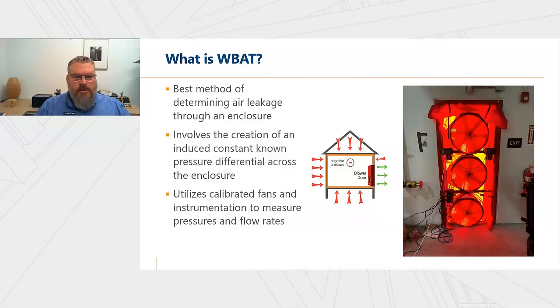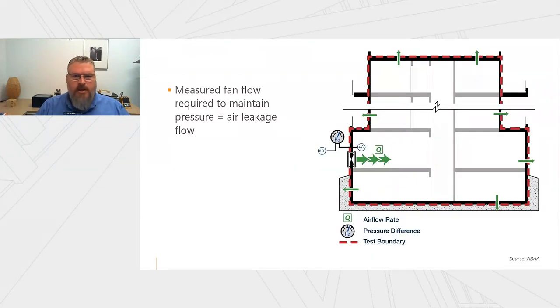And then, of course, we're using micromanometers to measure the pressure differences, typically between the interior and exterior of the building. Sometimes if you have a lab enclosure or an auditorium separation or something within the building, that might be between two spaces. But usually when we're talking about this, we're talking about the inside to outside delta P, or the difference in pressure. And theoretically, it's pretty straightforward.